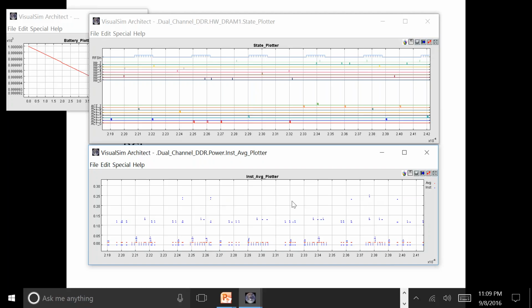This is going to tell you, for example, right here, I want to understand why I have these blue dots, which are causing these peaks. Because if I have those, it's going to cause me to have to plan my heat insulation, my cooling for this level, not at this level, which is where the overall power statistics are. So at this point, what I'm looking for is, are my signaling correct? Are my addresses correct? I'm looking at clock by clock what is happening in terms of behavior of the system. You would use the cycle accurate building blocks that we provide.